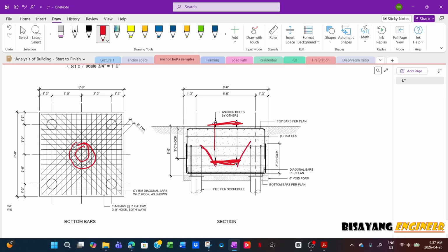And then the same situation here. What I did was I just have to make sure that the shear plane of the cone will intersect with the, aside from the actual pull out from the concrete. And then this is a screw pile, so all the forces from the pile cap will be transferred to the